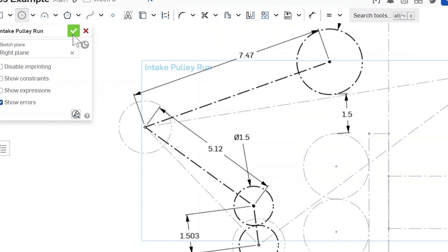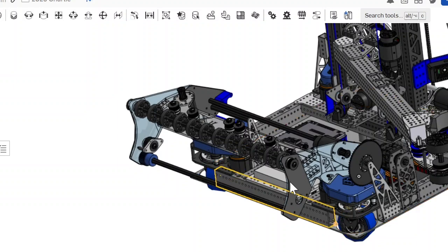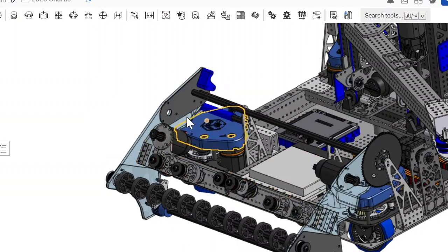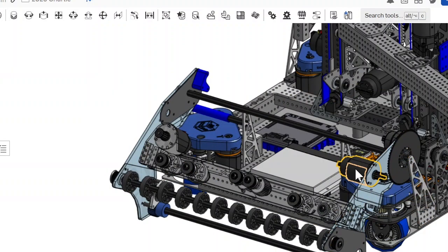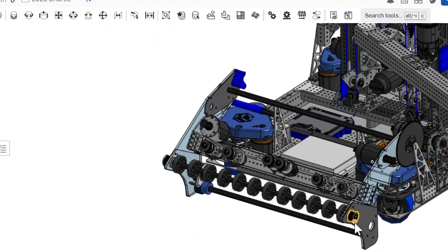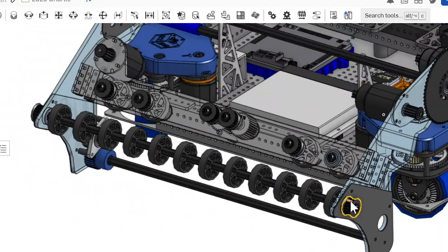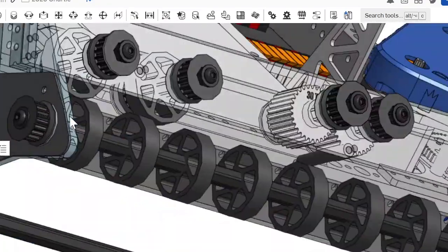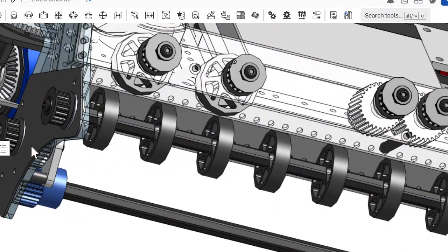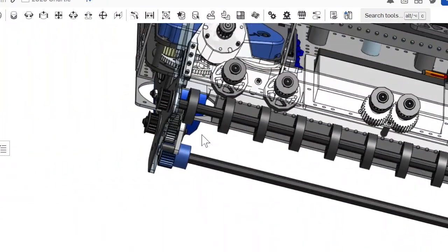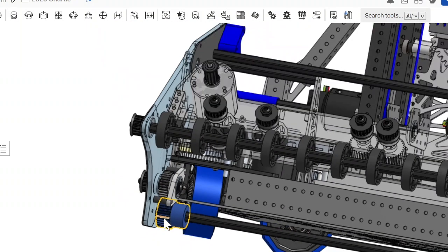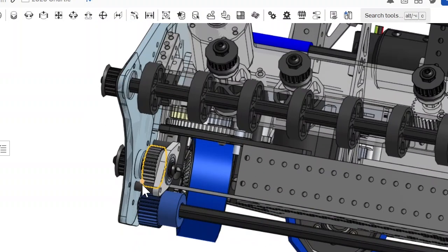Now here's an example intake with the same idea. It's a flip down intake that has a motor mounted right over here. That motor runs to the first set of top wheels here, and then it goes across. That shaft is still spinning, rotates this pulley out here, goes down and turns this meshing gear, and then this meshing gear runs a slower gear that spins the bottom shaft.